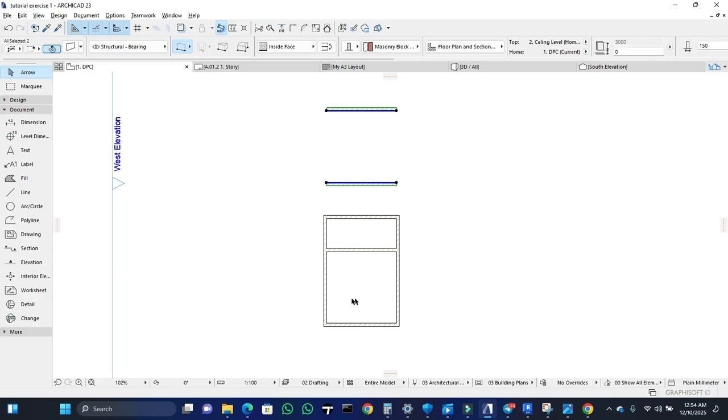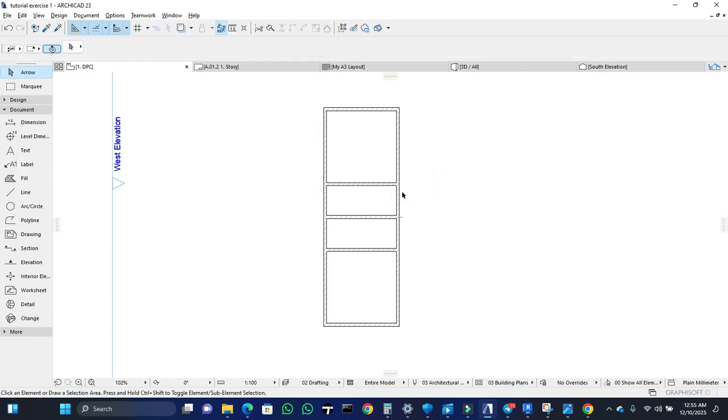So now that we've done that, you can join the perpendicular walls. We don't need to go joining this one first before this one. You can just join this one to the last one and we are good to go. So we select all the walls that are involved: 1, hold your shift key, 2 and 3. Having selected them, you just click on intersect. So all intersect. As you can see, it's all good.